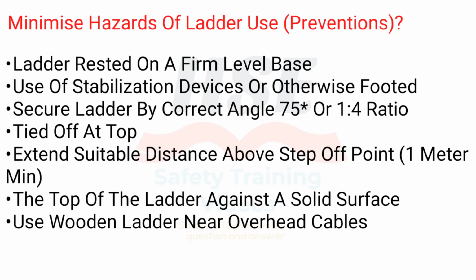Minimize the hazards of ladder use, preventions. Rest the ladder on a firm, level base. Use stabilization devices or otherwise foot the ladder. Secure the ladder at the correct angle, 75 degrees or a 1 to 4 ratio. Tie off at the top. Extend a suitable distance above the step-off point, 1 meter minimum.